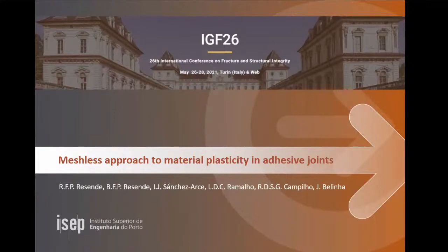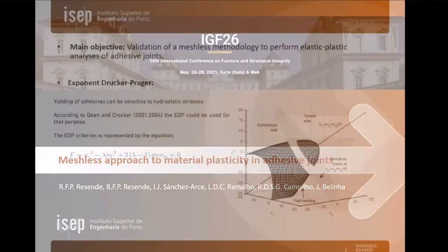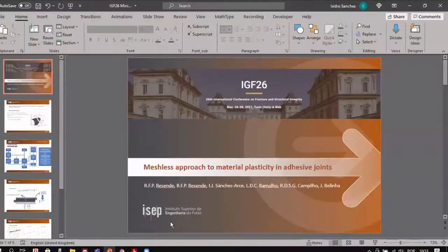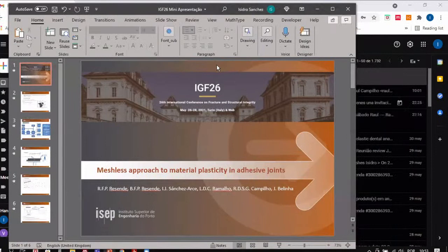Anyway, besides that, the theoretical or analytical techniques for analyzing adhesive joints, which are based mainly on closed form equations, are based on elastic models, elastic adhesive, elastic adherends. In the case of finite element modeling, using elastoplastic models is more or less straightforward until we arrive at the next point.